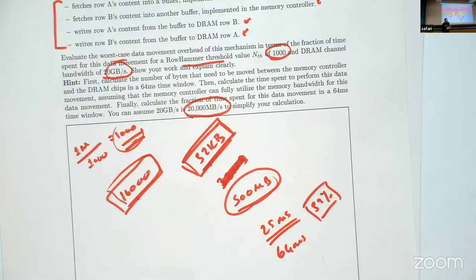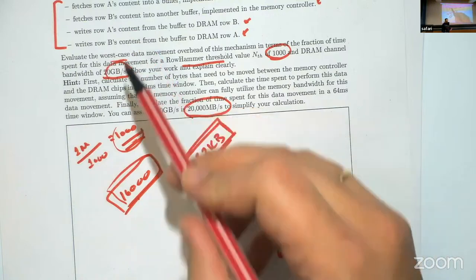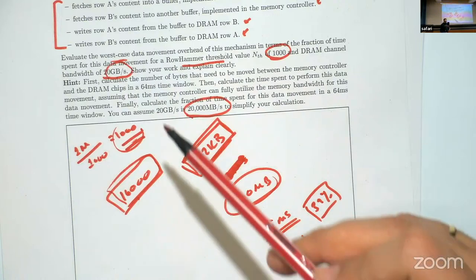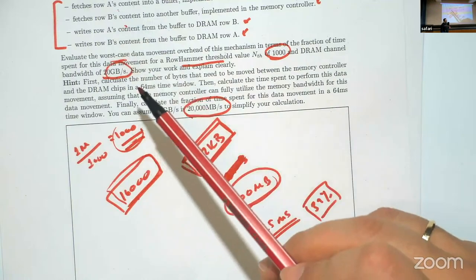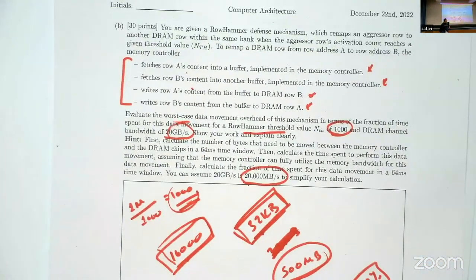the activation budget you have in that limited time window. So you can dedicate some of that budget to some rows and some of them to some other rows. Or you can put all activations on a single row. So here, the RowHammer defense mechanism already guarantees that there is no bit flip. But every 1,000 activations will trigger this kind of operation. So you're right that it doesn't have to be particularly row A and B for every single operation. This row A and B does not necessarily need to be the same row A and B for all operations here. So it can be from different rows.